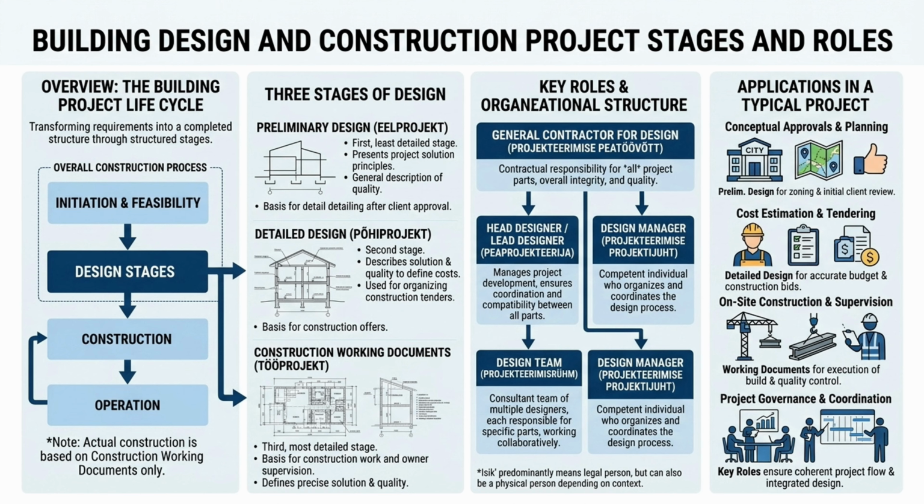The last and most detailed stage is the construction working documentation, or tööprojekt. This document lays out the technical details necessary for building and quality supervision. This phase defines the exact solution and specifies the required quality for every element. Importantly, in actual practice, construction work can only begin once these documents are ready. The preliminary and detailed design alone are not sufficient for on-site work.